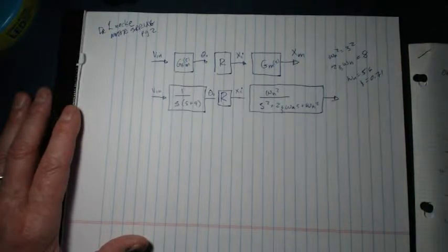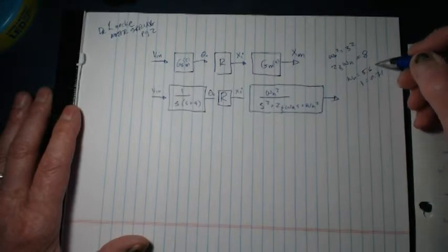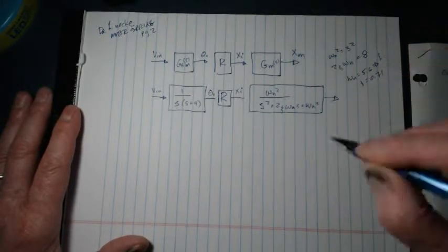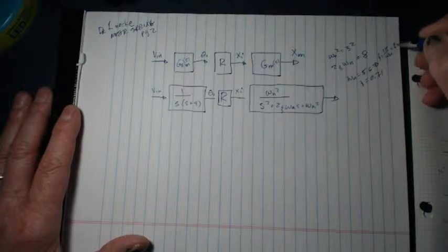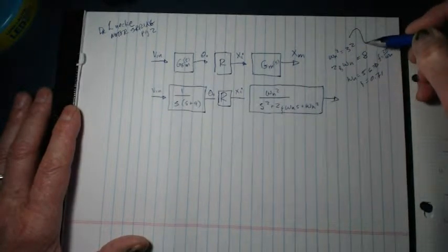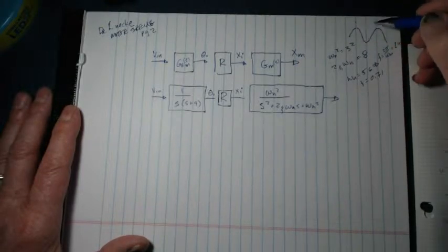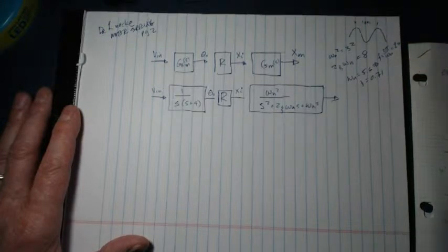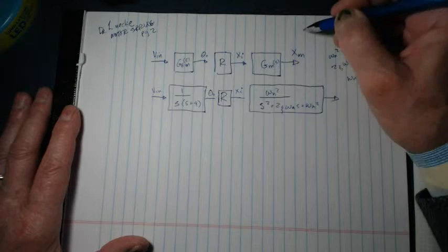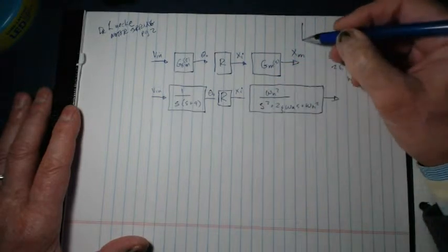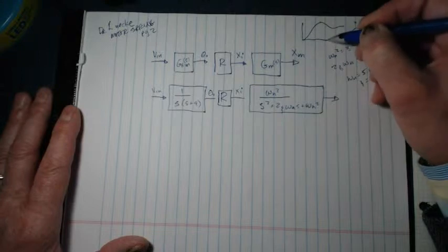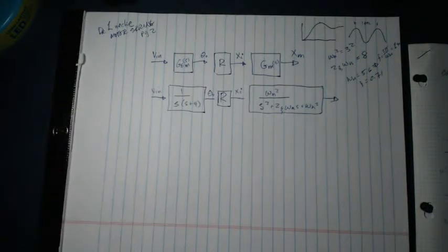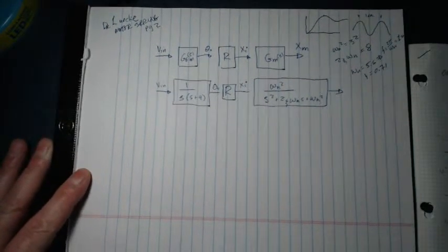And so if we wanted to look at what the response of that system would be, the period is equal to 2 pi over omega n, that's about 1 second. So our spring is going to have a period of about 1 second. And it also has a damping ratio of 0.707. So really, if I just put a unit step input on that one, it's going to damp pretty quickly. And we can describe that using our generic response characteristic curves.